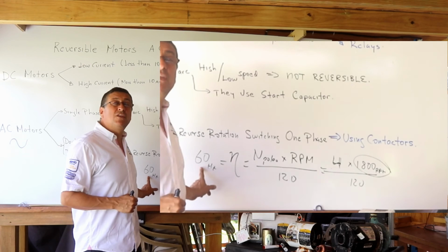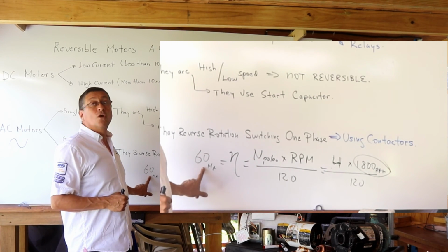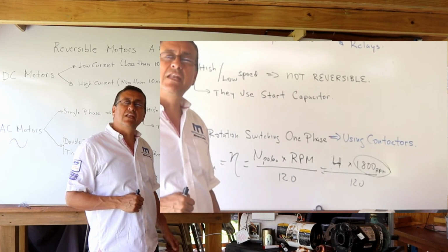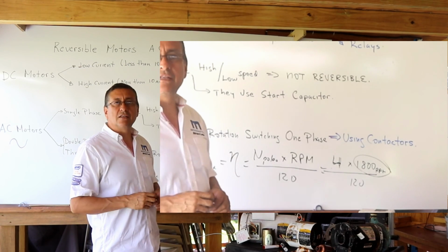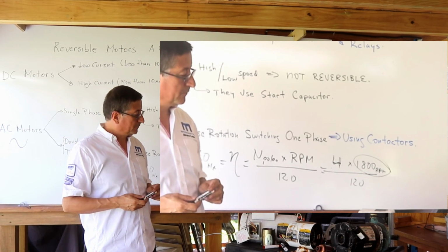What about 50 Hertz for European power? For 50 Hertz, with 4 poles on the rotor, you need to run the generator at 1500 RPMs. I explained that formula in detail in another episode of Chapter 10.